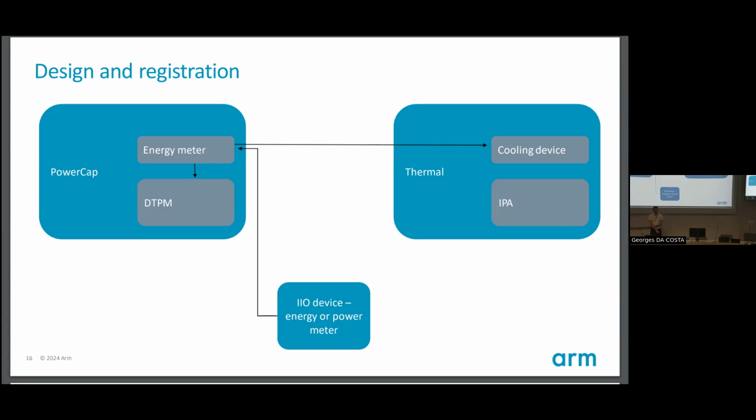Yes, I think it will make more sense to have a cooling device directly interacting with the power information from DTPM abstracted. So we can have a generic, power-based cooling device, without using the energy meter but using DTPM directly. So we basically have get and set power, and then we have the backend. That could be the energy meter or whatever.